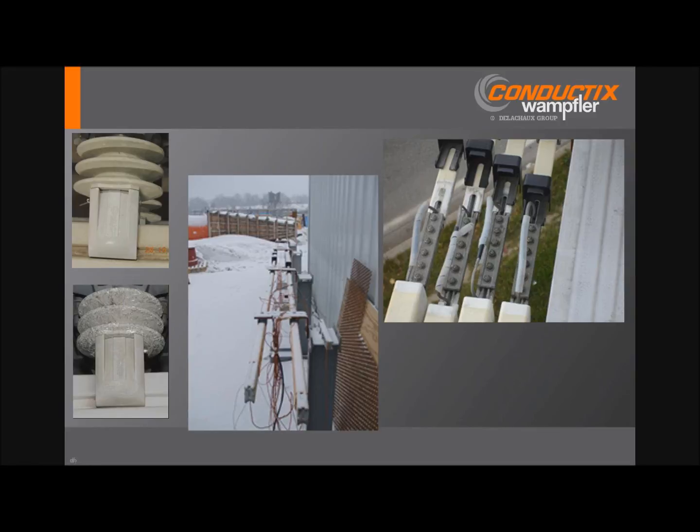In fact, one APM in a tropical environment with a lateral contact exposure suffers very, very high shoe wear every time it rains. And it takes a while for that graphite to be redeposited on the rails and the shoe wear goes back to normal. So where possible for open conductor systems, a bottom running or bottom contact orientation significantly reduces the effects of precipitation. In cold climates, the center here, heater wire systems can be an effective way to prevent the formation of frost and ice, but they're not intended as a thawing system.